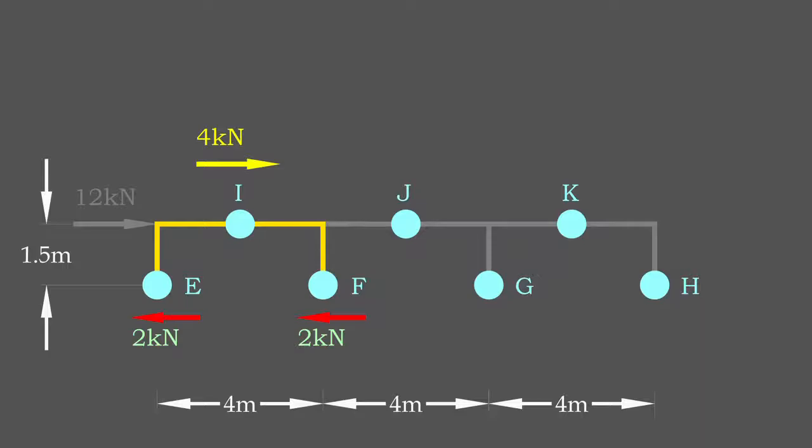First, we determine the shear force developed in each column. To do so, we divide the lateral load evenly for each subframe. For instance, consider a 3-bay frame subjected to 12 kN of lateral load.